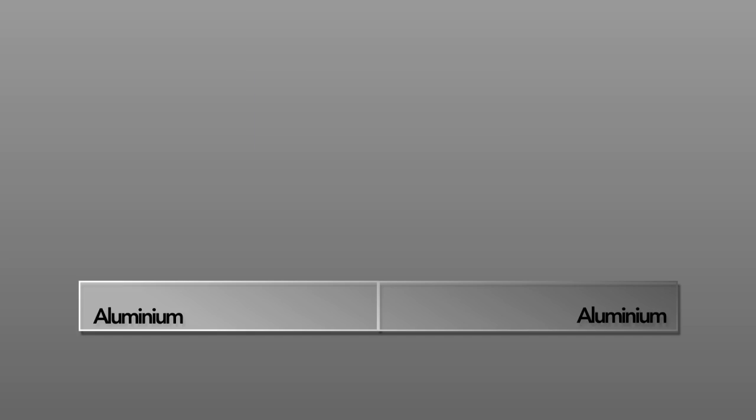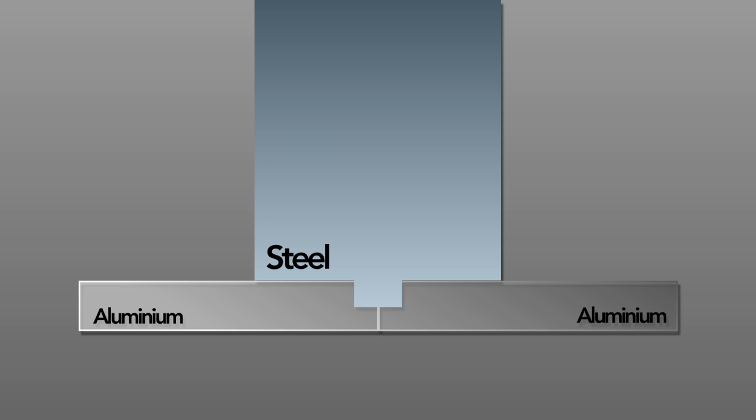You also need a welding tool which penetrates into the material. As soon as you start penetrating, the combination of rotation of the tool and the force will create frictional heat at the interface between the tool and the workpiece. This frictional heat will correspond to a certain welding temperature.